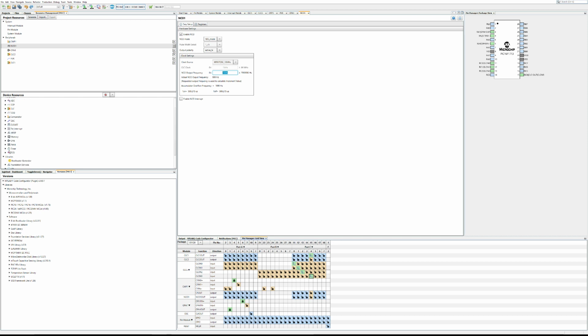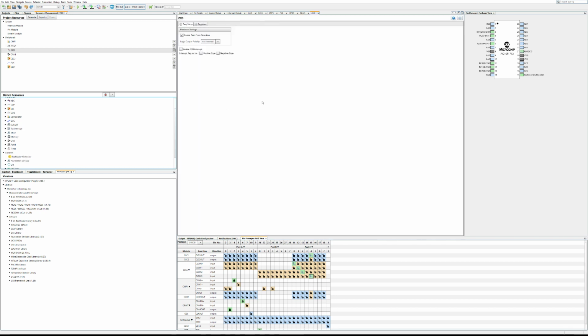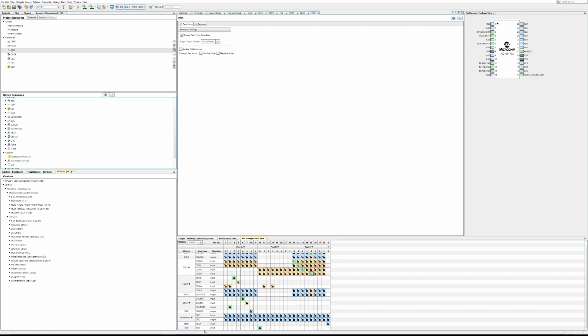Is there anything else I would like to go over here? There's a zero crossing detector. Very, very simple. Just input on it and feed an AC waveform to it. If the waveform is going to be higher peak than VDD or VSS, then you should use a series resistor, but it can tolerate input resistance of up to at least a megohm, probably a bit more, which means you can even use it with mains.